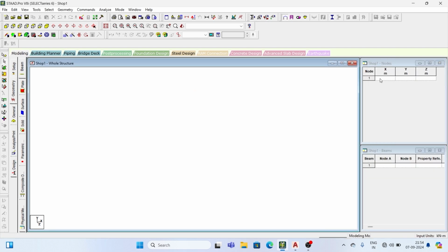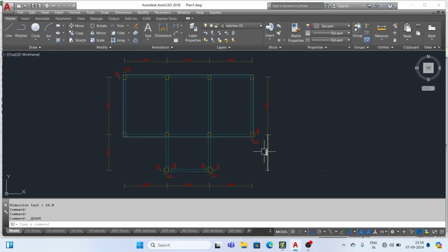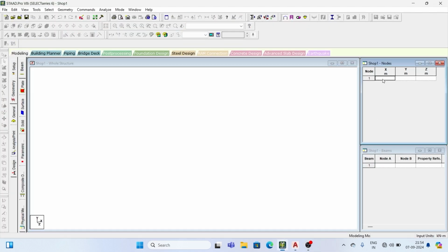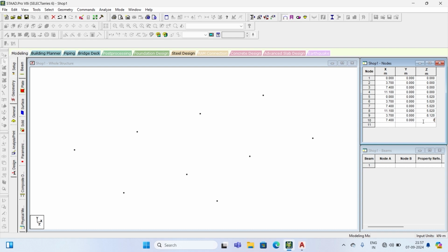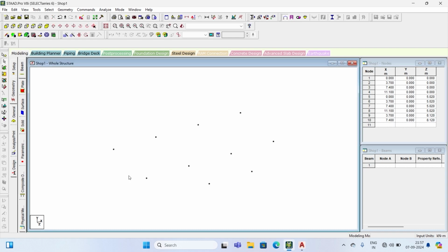Here we directly assign our grid points over here in this box. You have your CAD drawing like this and you have all those grid points, and you take these XZ values, here in CAD it's XY, and put them as grid points in STAAD like this. Now we go to this tool. This is the tool to bring the front view or the view from the positive Z axis, and it's here.